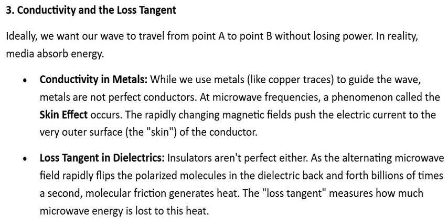3. Conductivity and the loss tangent. Ideally, we want our wave to travel from point A to point B without losing power. In reality, media absorb energy. Conductivity in metals. While we use metals, like copper traces, to guide the wave, metals are not perfect conductors. At microwave frequencies, a phenomenon called the skin effect occurs. The rapidly changing magnetic fields push the electric current to the very outer surface, the skin, of the conductor.